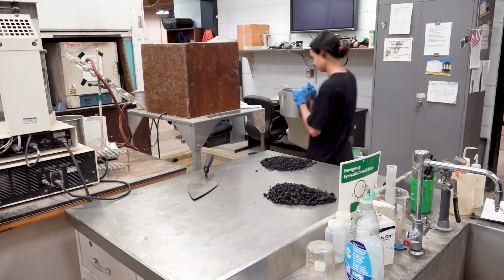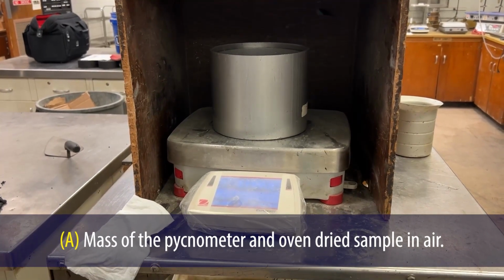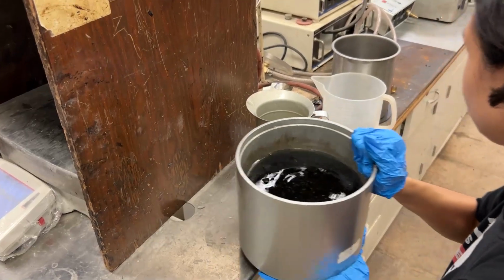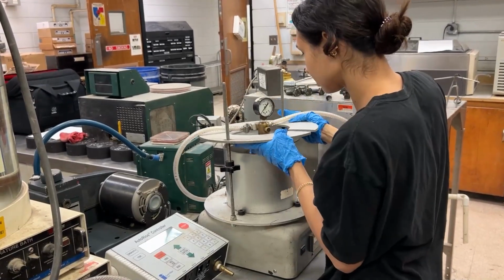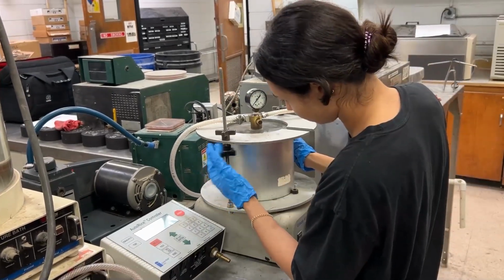Next, place the pycnometer and the sample onto the scale and record the weight of the mix as A. Next, add water to approximately an inch above the sample. Carefully place the pycnometer on the vibrating table. Secure the pycnometer to the vibrating table by placing the vacuum plastic lid with O-ring gasket onto the pycnometer, ensuring you have a good seal.